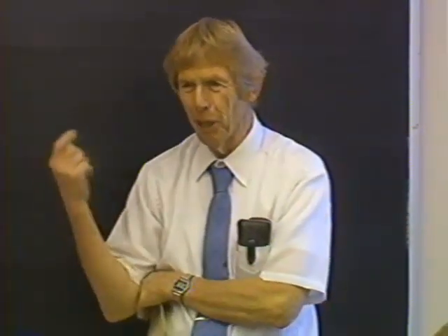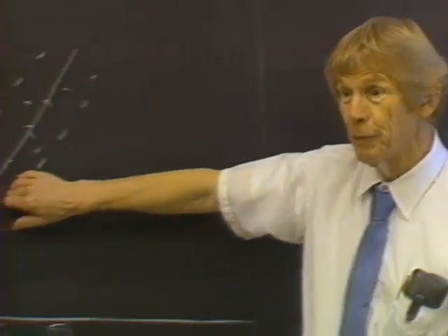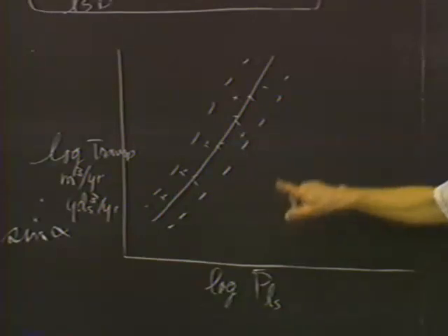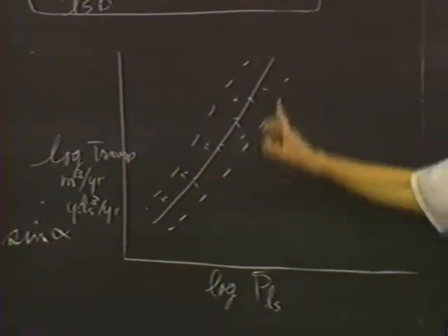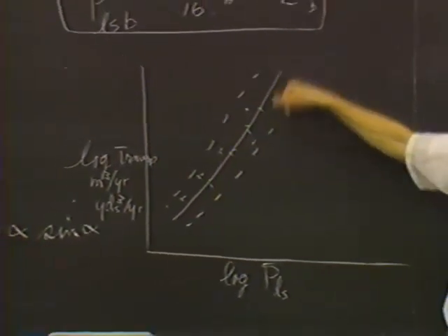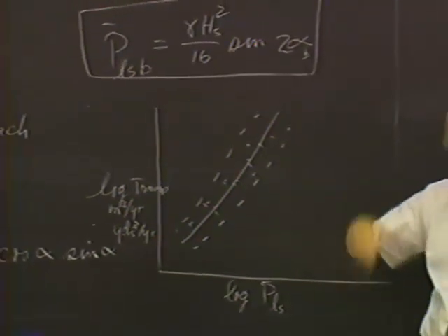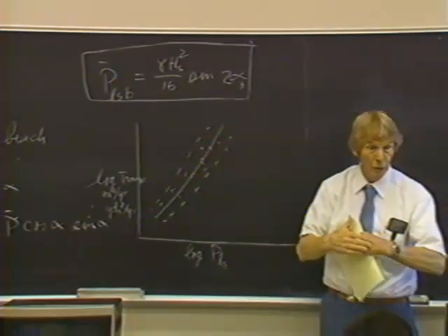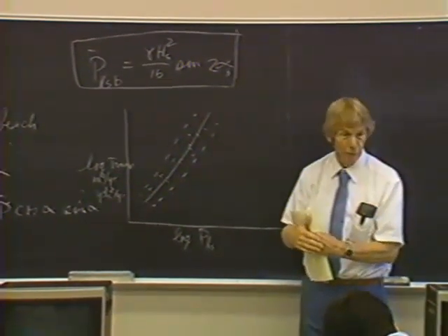So just to give you some idea of the nature of these numbers. Well, this is purely empirical, and it's plus or minus 50%. And often, because you calculate sand transport in one direction part of the time and another direction the other part of the time, depending on where the storm is out in the Pacific, you're taking the difference between two large numbers, which means that the numbers aren't very reliable.